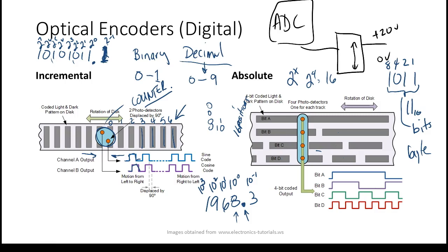So one option we've got is to return this thing to the same spot. Anybody got a printer at home? Odds are they use this encoder. When your printer's turned off and you turn it back on, besides cleaning the head, you find that it's finding itself, right? You hear that thing, and normally it'll have a sensor, usually an optical interrupter, and a blade on the print head. It'll come over and block that blade. A lot of times they send it more counts than it can do, and it'll just stall up against the side, and it finds itself that way.